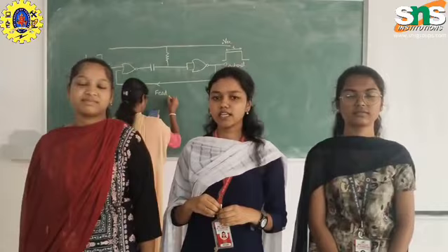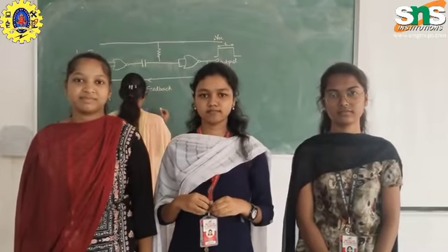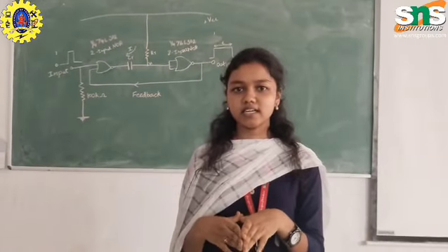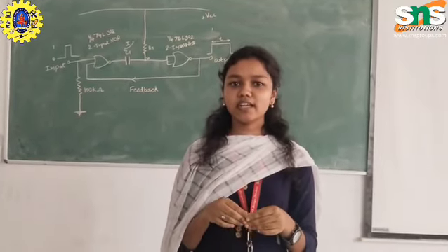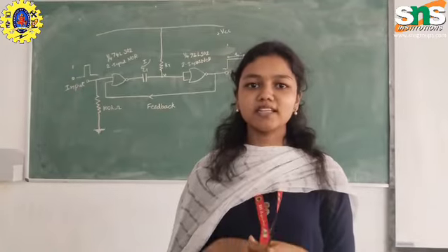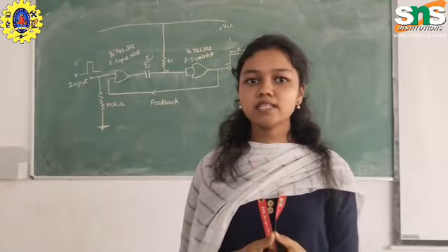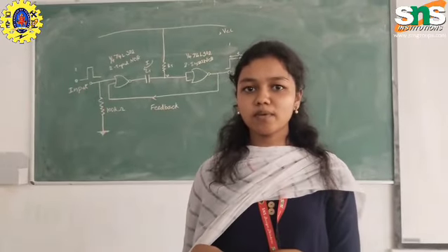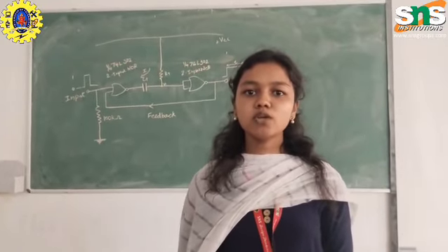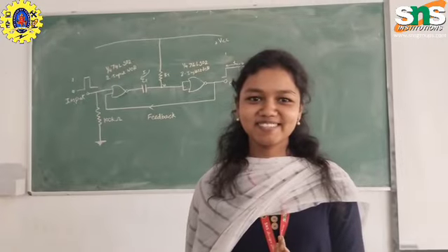Now we are going to do a case study on the topic of monostable multivibrator using the concept of design technique. Multivibrators are sequential regenerative circuits, either synchronous or asynchronous, and are used extensively in electronic timing applications. Multivibrators produce an output waveshape resembling that of symmetrical or asymmetrical square waves, and as such are the most commonly used of all square wave generators. The monostable multivibrator belongs to a family of oscillators commonly called relaxation oscillators.